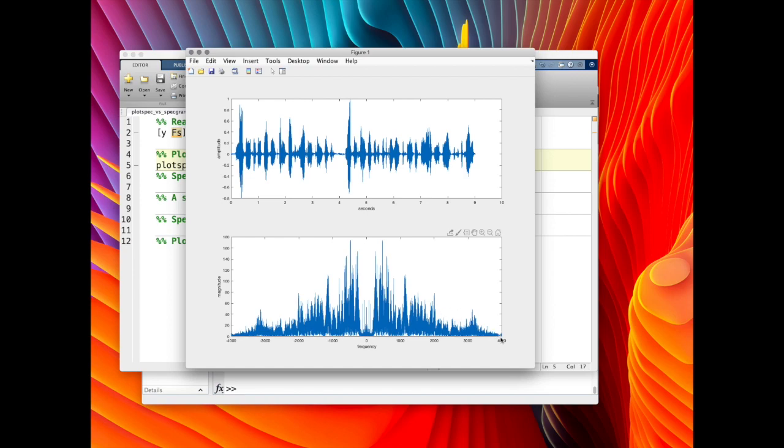We talked about the maximum frequency you can have for a signal sampled at 8,000 samples per second is 4,000 hertz. Okay, so this goes from minus 4,000 to 4,000, and you can think of it as that blob kind of shape that we've been talking about in class. So following my mouse cursor here, there's the blob kind of shape that we're talking about.